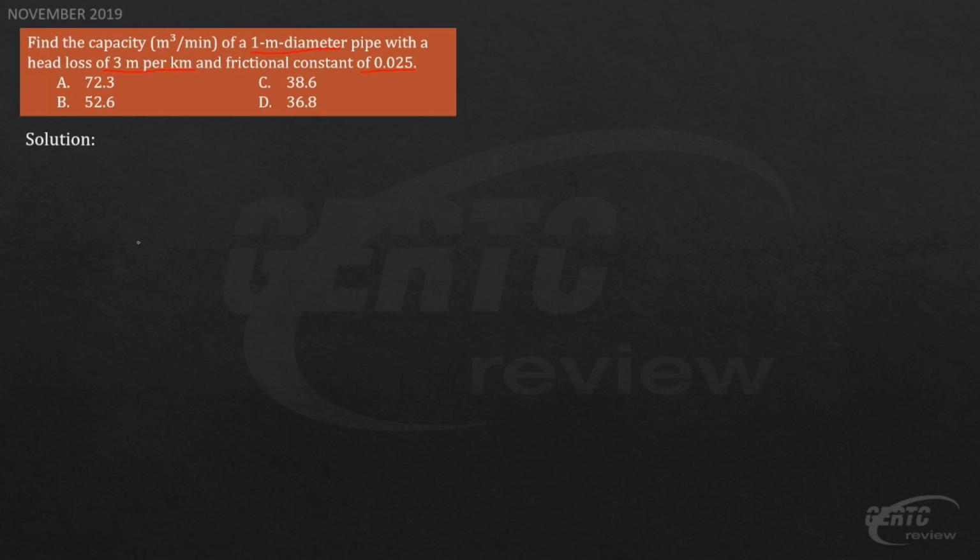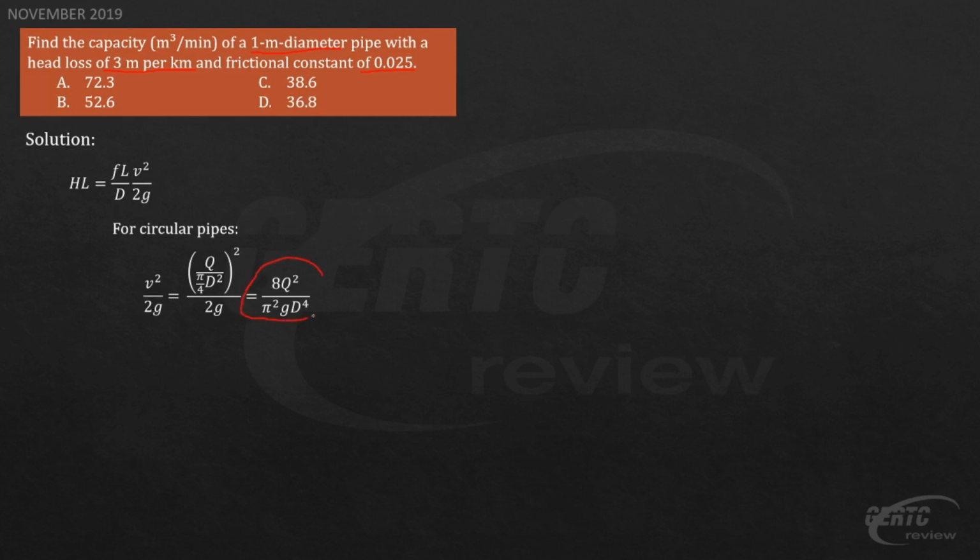Okay? So, the formula is head loss is FL over D times velocity head. And alam natin that for circular pipe, velocity head is equal to V squared over 2G. V is Q over area. So, area of the circle. So simplifying that, it will be in terms of Q, that is 8Q squared over pi squared G D to the fourth. Magandang ma-memorize mo rin to, no? Any unit will do here. Any unit will do. That is the velocity head in terms of the discharge. So that if you will substitute this value here, ilagay mo yan dito, ito yung magiging expression niya. Na? Or simplifying that, that will become ganon.